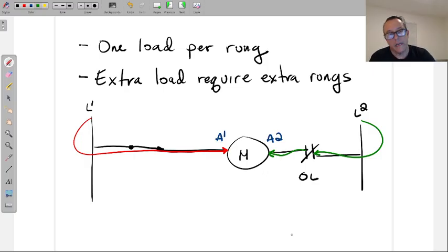So motors, and only motors, are a machine, are a control system that has a means of protecting it from that situation. Now, all loads have that, right? The breaker is supposed to trip when too much amperage is on the load, or when the load is creating too much amperage. But motors are not protected from an overload by a breaker. Motors are protected from an overload by the overload. And by the way, this is a relay. Technically, it's an OLR, overload relay.